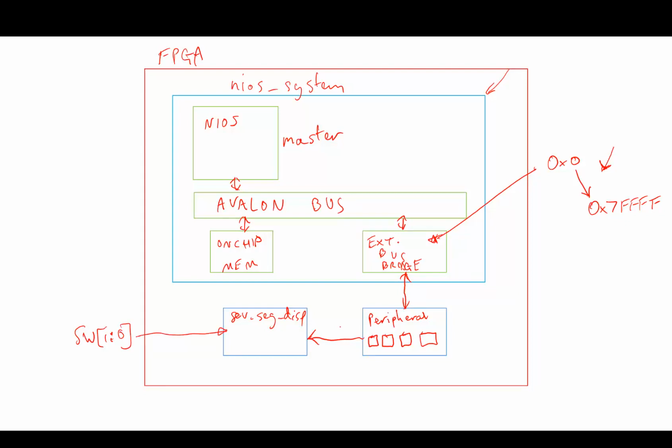Based on those 2 switches, the connections here are from the actual direct registers within that peripheral block. Depending on these 2 switches, it's going to choose the 16 bits of one of those registers and do a conversion. So we'll have some module in here, binary to hexadecimal, or binary to 7 segment, whatever.